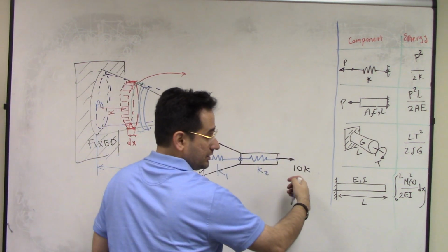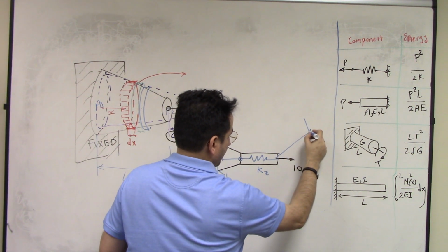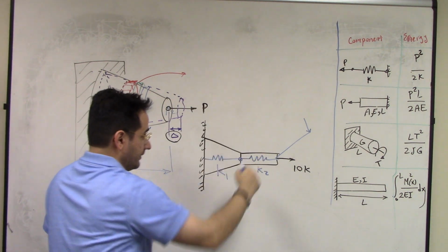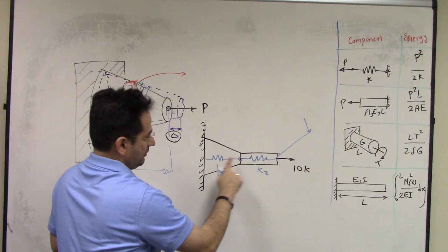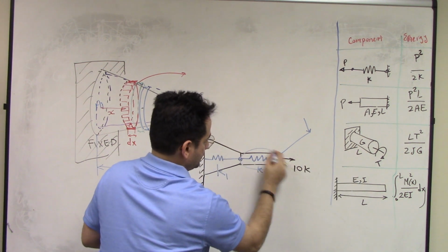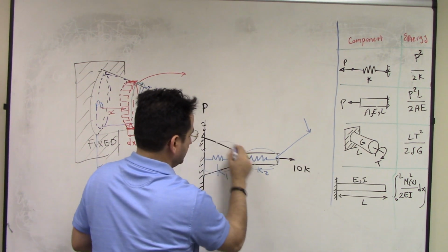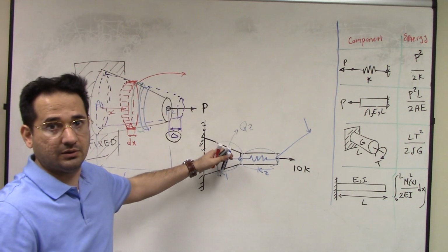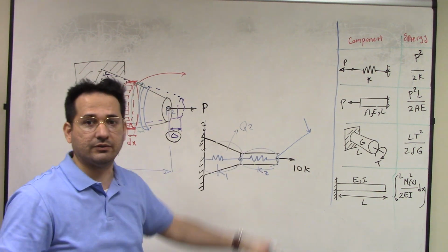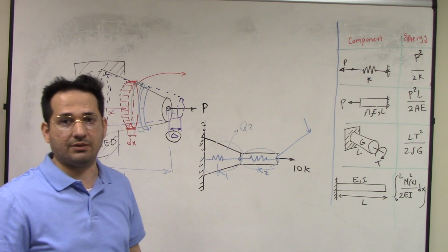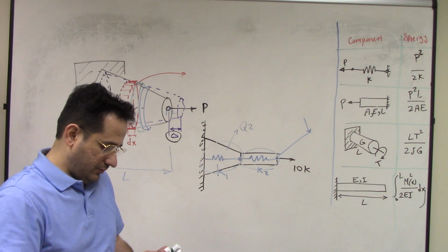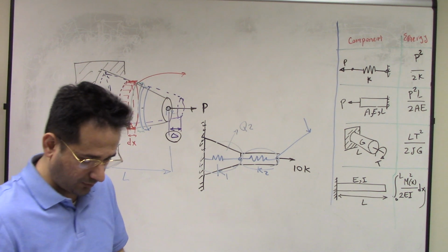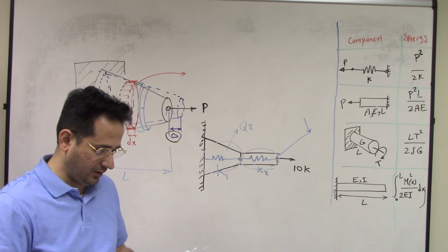Also, if you have a torsion, because you have an arm and you have a loading on that rigid body, so you're going to have a torsion, right, a twisting effect. Then the torsional spring constant of this constant-section bar is right here. And the one you get from question number 2 is the torsional spring constant of the tapered one. Then you can immediately find the effect of torsion. In fact, you can solve the last problem. So this is just a brief overview of what you need to know before you attack this homework problem.